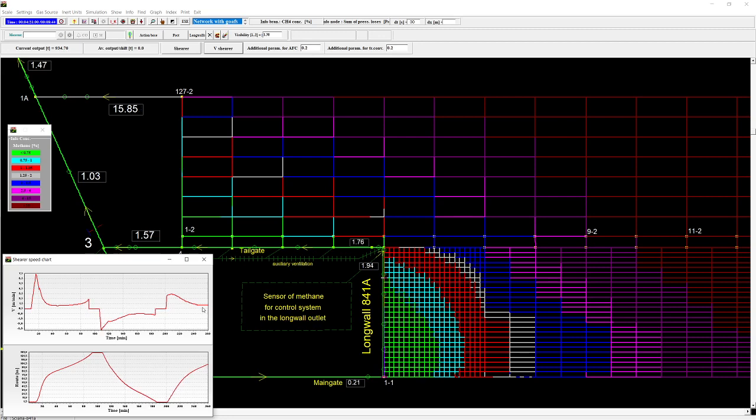For not controlled operation, we would have here several emergency power shutdowns, after which the whole longwall has to be ventilated and checked that the level of methane is reduced to permissible values, which causes a long break, reduction in production level.